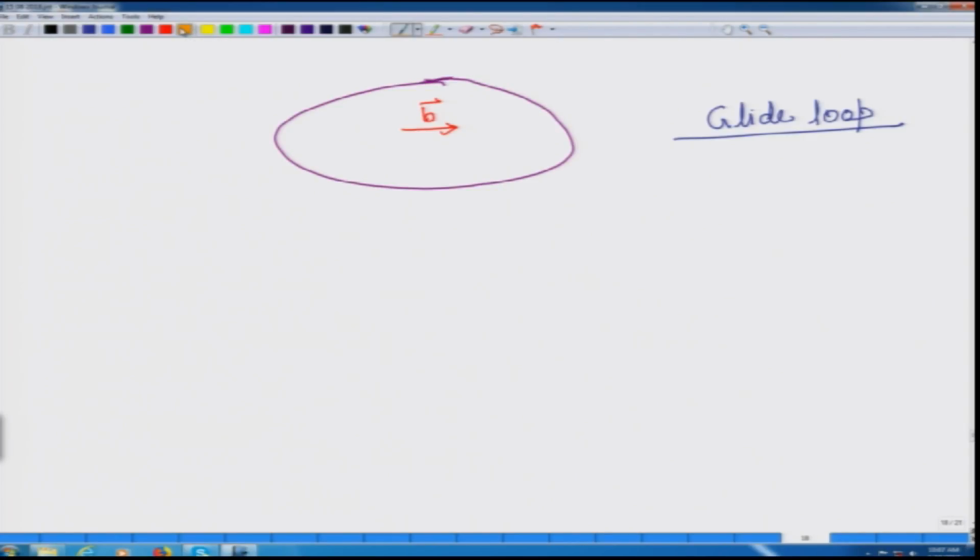So, let us look at different aspects. This is the Burgers vector, and the line vector is continuously changing along this line. Somewhere around here the line vector would be, let us say we have taken a convention that the line vector is going like this. It cannot change sense arbitrarily, so it is continuously going like this.